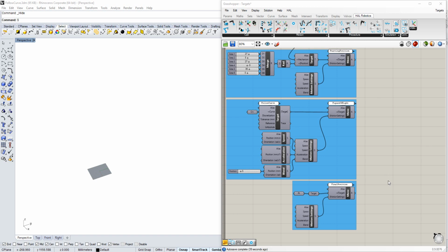For those of you that have already tried passing several motions into one controller, you'll have noticed that the controller doesn't like it. That's because the controller is prepared for multi-robot support and assumes that each procedure that's passed to it is for a different robot. In this particular example, we've only got one robot in the controller and therefore need to pass just a single procedure. We're going to combine these procedures into one using the combine component.